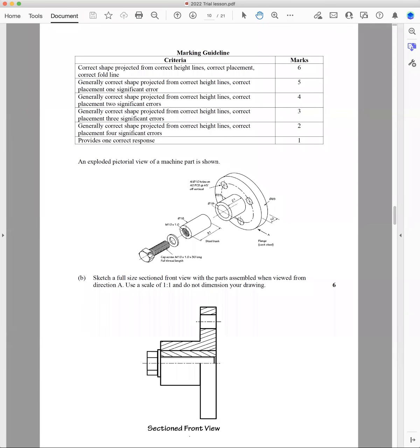And if you're only showing one view of this bolt, look, see how this is shown here. If you're looking there, you'll only see 2 faces, and that's not on. You're not allowed to do that if you're only showing one view, because it could be a square. And so you've got to show 3 faces here. And the diameter of a washer is 2D, and the cross corners of a hexagonal nut is 1.8D.